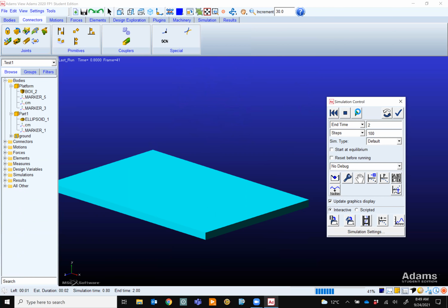Then this command passed through that one because we didn't yet tell the program that these two can interfere with each other, right? They have contact. That's why in the Adams model video that I showed you, I cheated, because I didn't specify that these two parts are going to clash. They pass through each other. Because of the visual, people think that it's moving, which is more impressive. But in fact, it goes up to a certain degree.